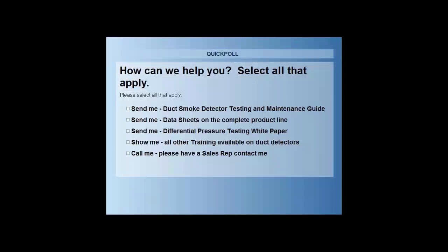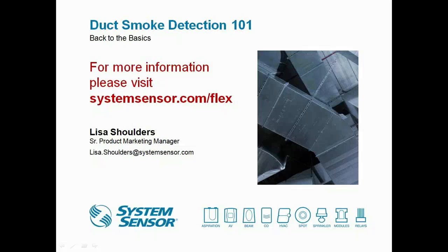So typically when people are installing intelligent duct smoke detectors, we recommend them always using the remote test capable head, just to ensure that they have the head that they need in place whenever remote testing or signaling may be required.